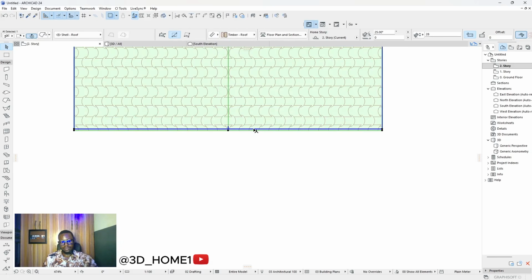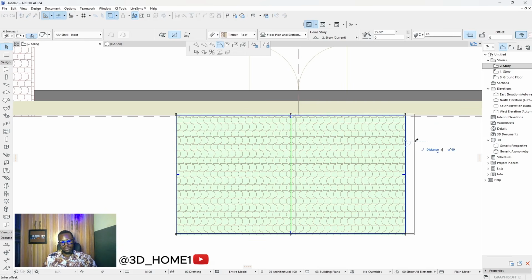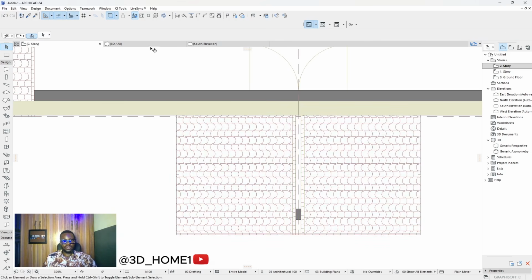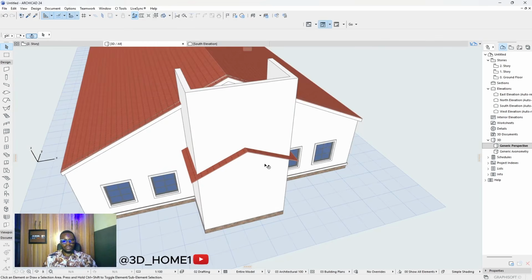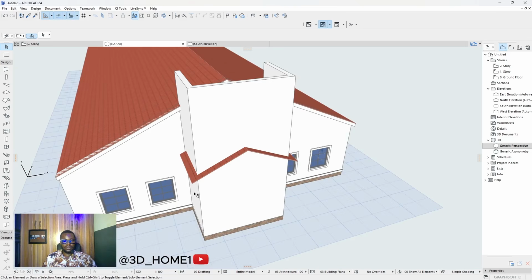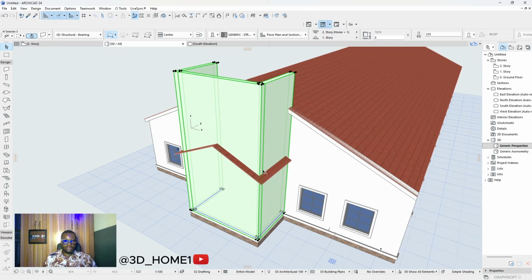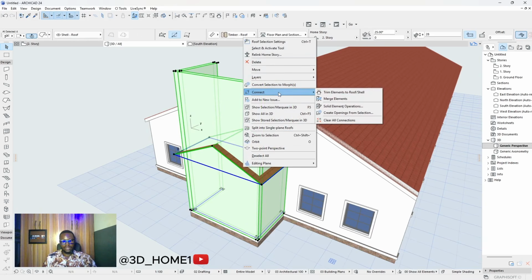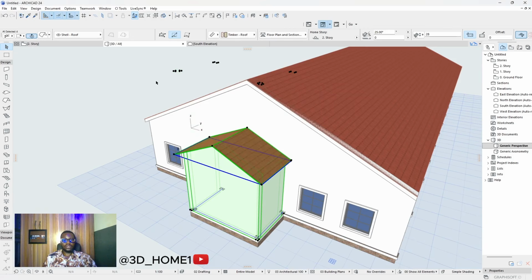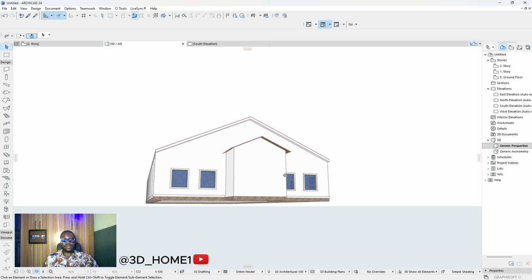Same thing. This is same angle. So this one we're giving here 300 also to outside. Another 300 to outside. I just hope it's not touching those windows. Yep, it's not touching the windows. So now click all these 3 walls, and then with the roof, right click on that corner, you say trim to wall, and you say trim. You see, that's how it's looking like now.